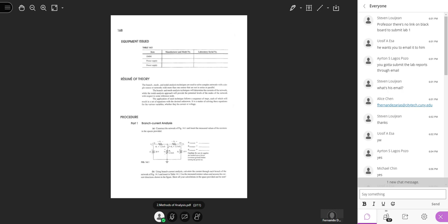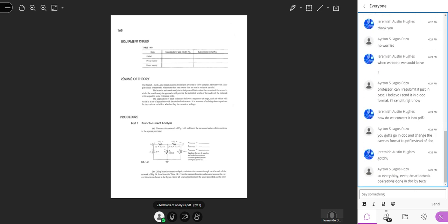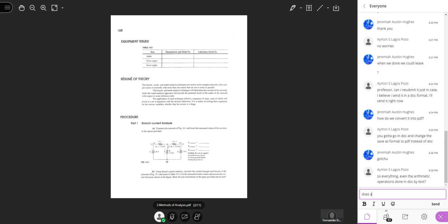Okay, another comment. Some of you, when measuring current, use the amp function to just show what the current is through the wire. I would rather you use a simulated piece of equipment, because when you tap into the wire just to show what the amp is, it does not show me that you know how to take a current measurement.